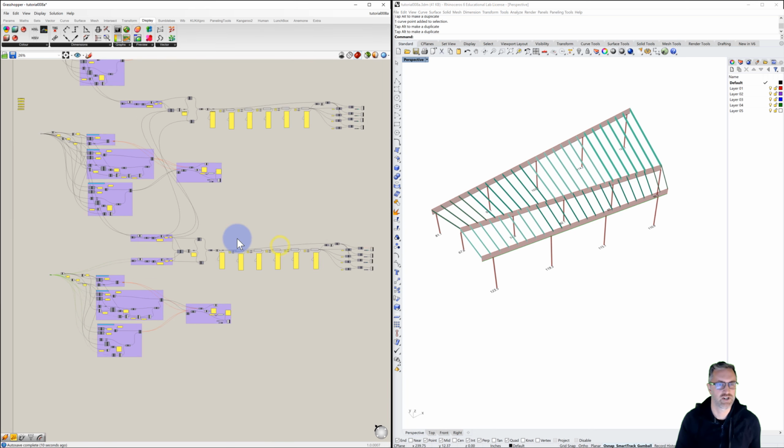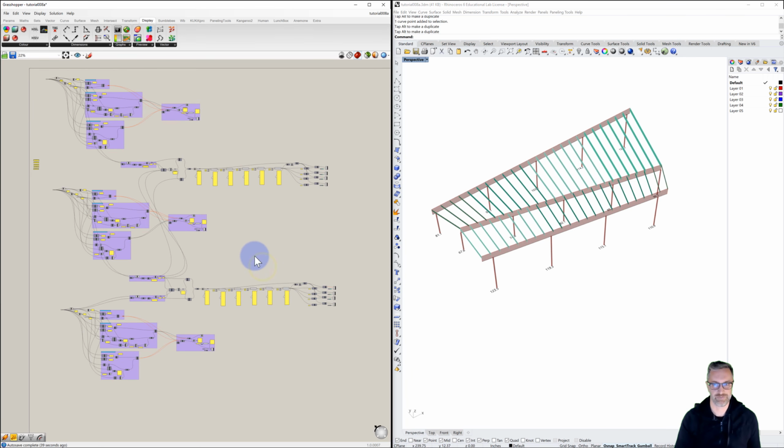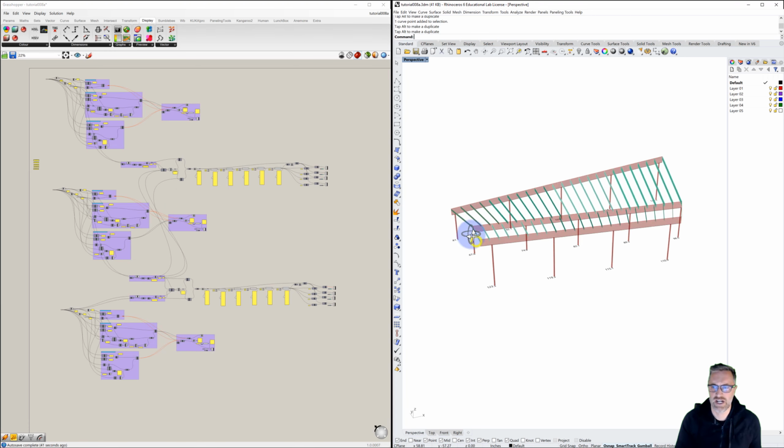and with a pretty simple copy, we can see as we zoom out on our Grasshopper definition, we've got what's driving our curve, our first curve, and produces the girder and the columns. We have all of this, which is the intelligence of the span of the rafters set between them. Our middle girder sits here, our last girder at the bottom, and then the set of rafters that span between those two is in the center here.